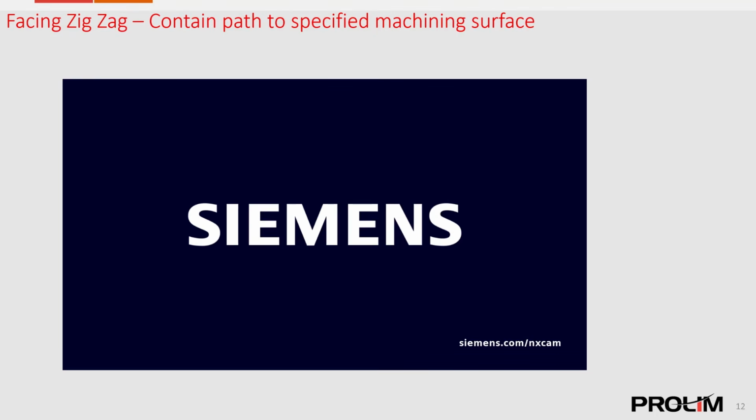So this leads to a much cleaner result. NX focuses only where it should, reducing toolpath clutter and ensuring that the operation does exactly what you intended. You'll also get support for trim boundaries and the ability to set the contain blank option, so either none or cut area, giving you even more control over how aggressively or selectively toolpaths are applied.